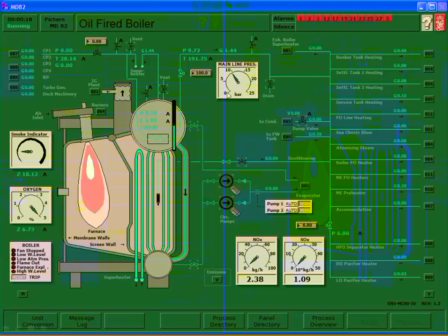And one important part to think about too: why don't I just take superheated steam and go to all my heating services? Why am I taking that superheated steam and going through the desuperheater, which, by the way, is typically about 2 to 4-inch pipe, running down the bottom of the drum and making about 3 or 4 passes and then out again?